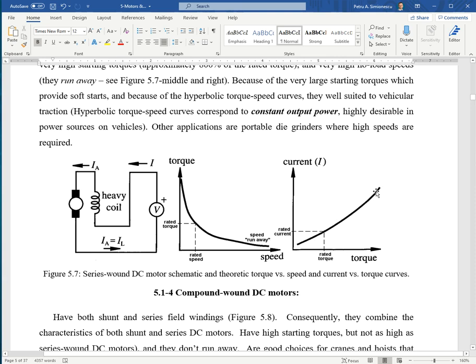Okay, the current curve looks as shown here. You can match the rated torque and get the rated current. Again, this is useful information, and by the way, the diagram should be given at a specified voltage. It could be for different voltages, so you can power a motor at 12 volts or at 9 volts, and the curves will look different, of course, and will be lower.